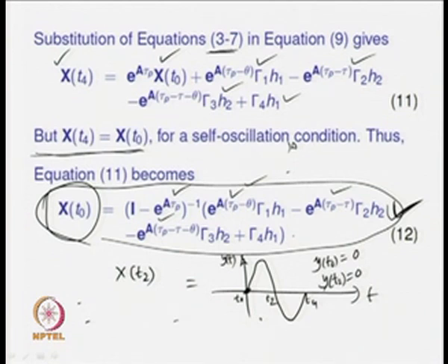So, when you substitute, C x(t0) is equal to y(t0) is 0. Similarly, C x(t2) is equal to y(t2) is equal to 0. Then we will get further simplified expressions for equation 12 and the other one. Keep in mind this can conveniently be used to find simpler analytical expressions, or nonlinear expressions, which can subsequently be solved to estimate the unknowns associated with the second order plus dead time system.